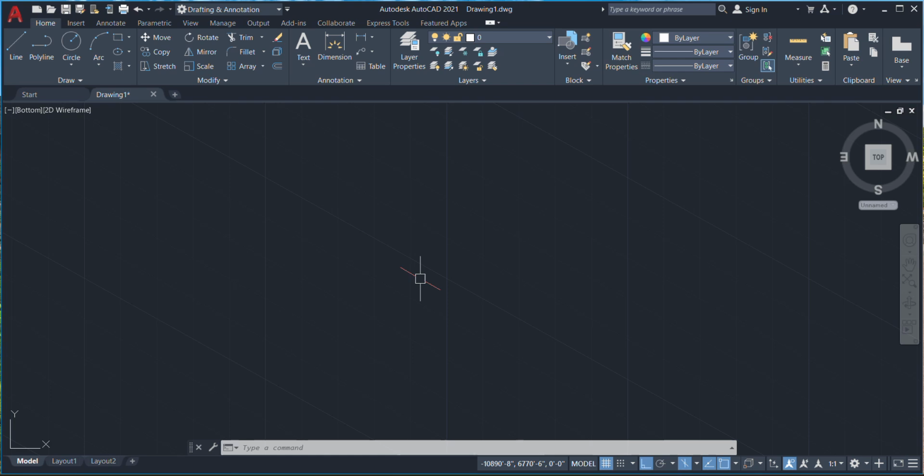Here I want to show once how to draw a diagram. Isometric is mostly useful for manufacturing purposes. Only in isometric can we show all types of dimensions in a single diagram. If we go with 2D, we have to take some sections to show all the dimensions. So with isometric view, in a single view, we can give all types of dimensions.